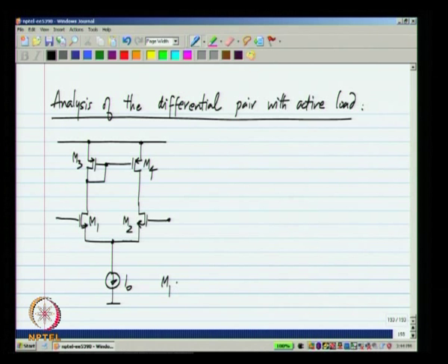As I have mentioned many times, M1 is identical to M2 and M3 is identical to M4. Okay. Instead of Vp and Vm, I will show it as a bias voltage plus differential or common mode increments. Now, the transistors will have some GDS values. Okay. In reality, they will be there and we have to include that in the analysis, and throwing all the equations together and analyzing it is not very useful. We have to get some intuition as well. So, that is what we will do.